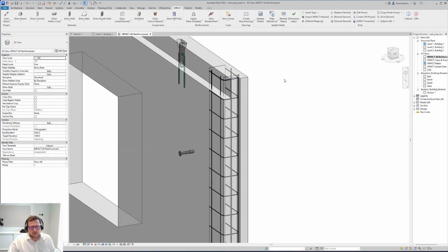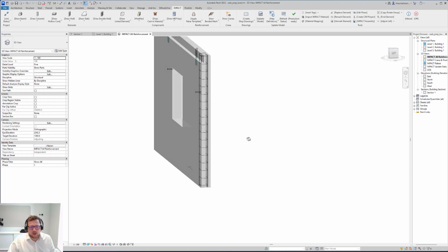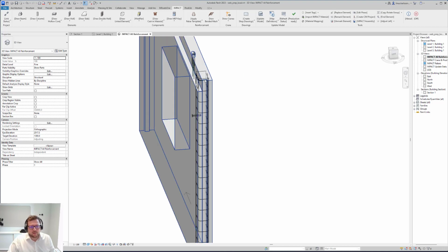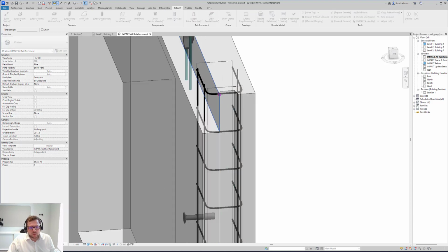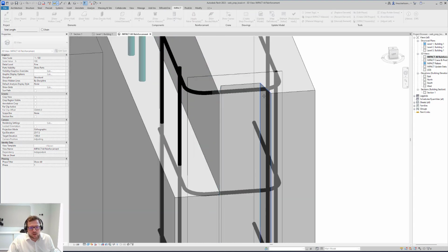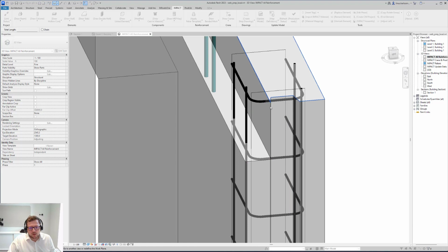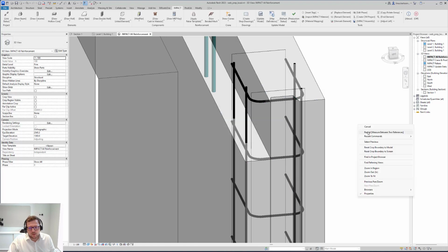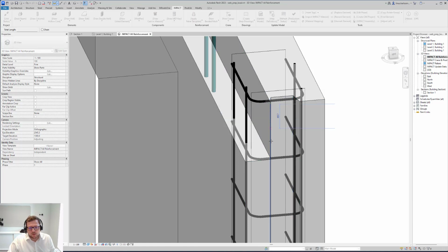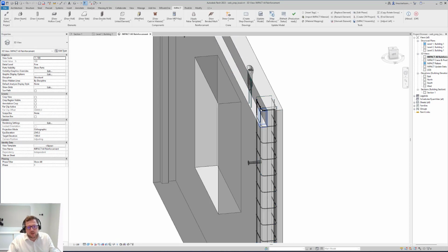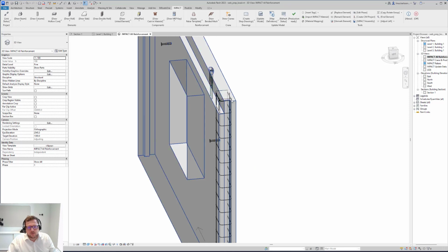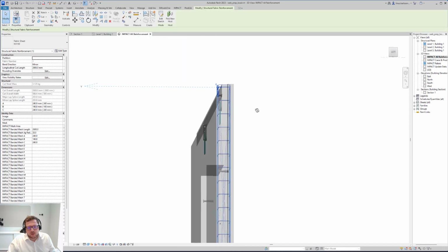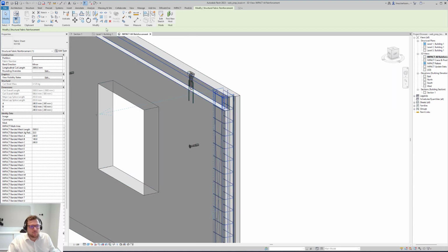But we can also see that I was not careful when I did it, so it's placed in the top here. So let's just make sure that it is fine. I will take the corner here, corner there and here. So it's 145 millimeters. And my cover is 20, so I need to move this one. Or actually, it's already in the cover, so that's fine.